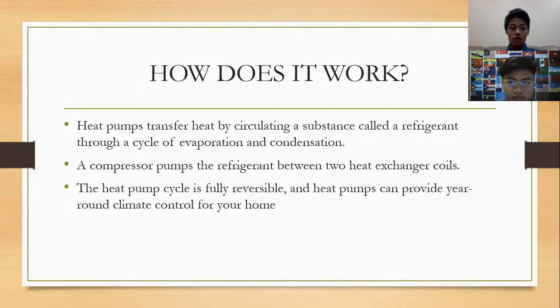The refrigerant flowing from the evaporator carries the thermal energy from outside to indoors. Vapor temperature is augmented within the pump by compressing it. The indoor coil then transfers thermal energy from the compression to the indoor air, which is then moved around the inside of the building by an air handler.